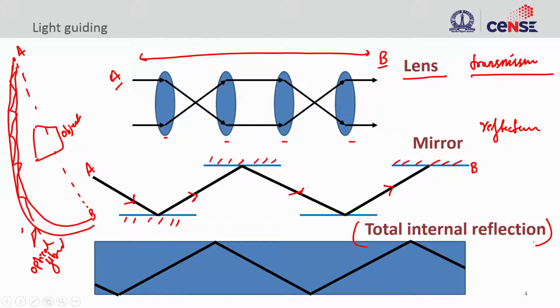So, this is the principle that we use, similar to mirrors. The light is getting reflected within the optical fiber, right, and confined inside without escaping to the environment, and this is taken care of by a phenomenon called total internal reflection that mimics mirror-like behavior. And this is how you can transport light in a denser medium, okay. So, you take optical fiber which is denser, and you can also take a silica slab, like our mirror. You can take a mirror and make light propagate through it. So, these are all the ways to guide light, all right.